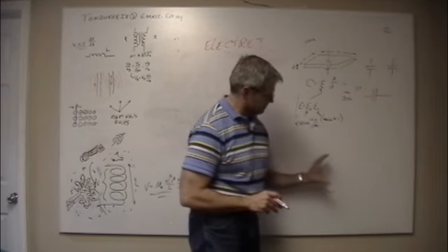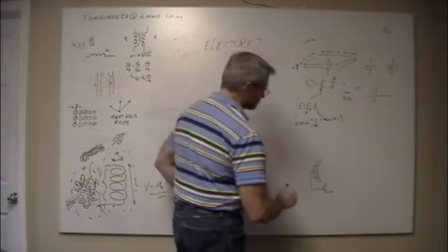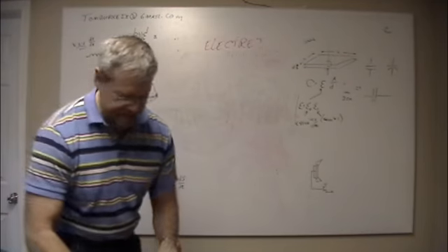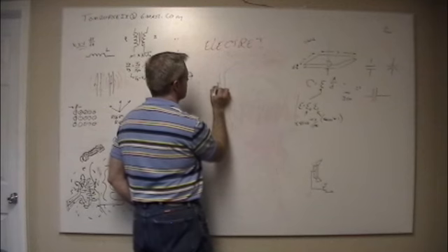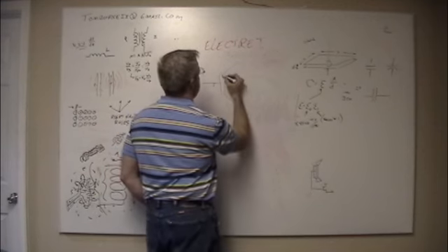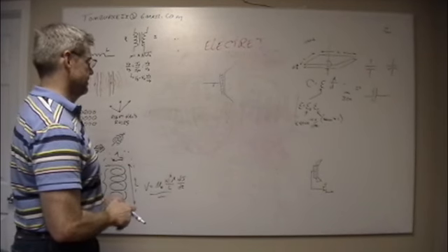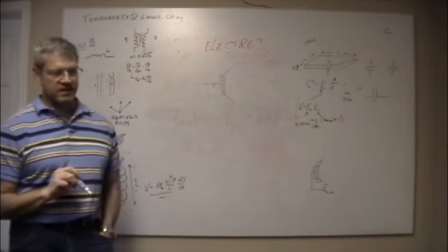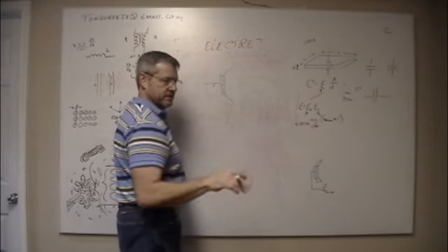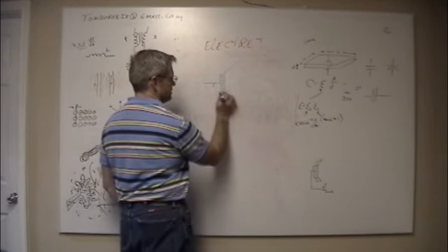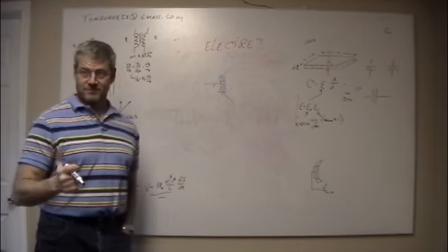I have my voice cone, right? And I'm talking, and it moves back and forth as sound waves impinge on it. And on the back side of this thing is a metal plate, and here is a squishy polymer. And what they do is they charge this. So that's loaded, so it's got extra electrons in it. So if this thing's just sitting idle, there's electrons in here, which means there's an electrostatic field in here. Yeah? With me?